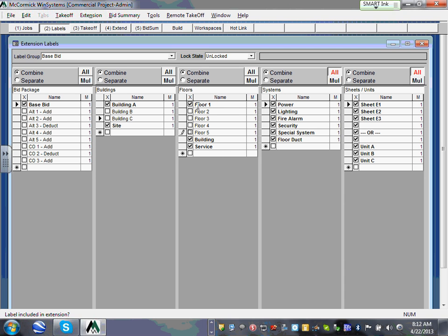Building and service. So we're going to be taking stuff under the floor, for the building, on the building, and for the service. As we trench and come to the building, that will be under service. Cool? Everybody knows this is really, you don't have to do any of these. You can put them all in one floor and do the takeoff, and the answer will be the same. This will help you manage the project. How do you slice the pie as you give it to your project managers and estimators to manage your project?